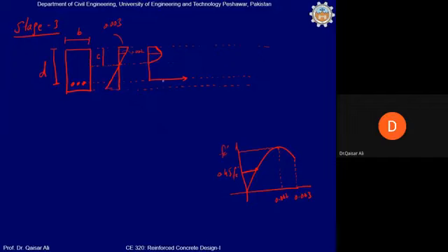Also, you know the value of stress in the reinforcing bar, it will be equal to Fy. Why? Because you have seen in the video that for a beam which is designed as per ACI 318-19, the steel would have yielded well before the crushing of concrete. This you have observed in the video. So at this stage, since the steel would have already yielded, we can take the stress value in the steel equal to Fy.